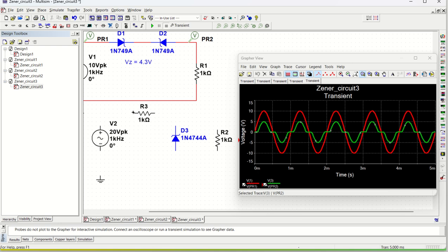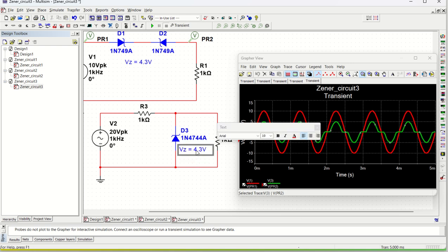And this is the way you can simulate the circuit for Zener diodes. Your aim is to make sure that the voltage at this point is such that the output voltage is greater than this 15 volt. So Vz is actually 15 volt for this. Let me just write it here so that you can always have a clear picture.